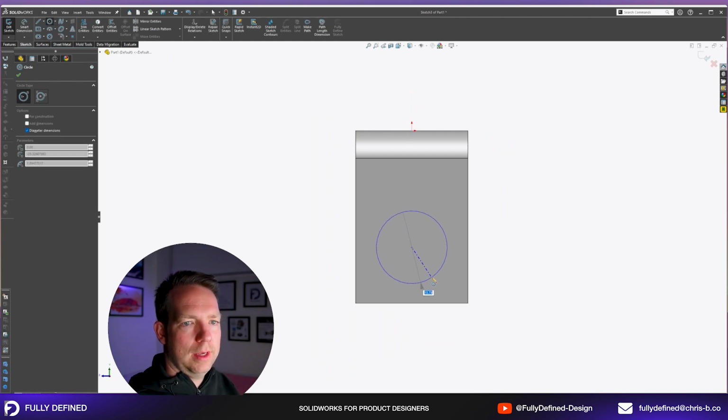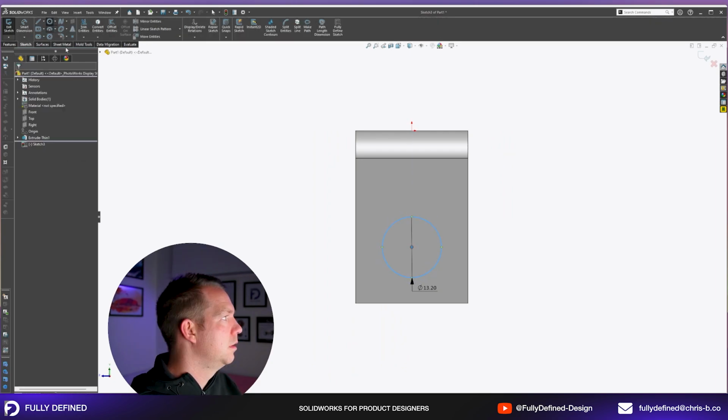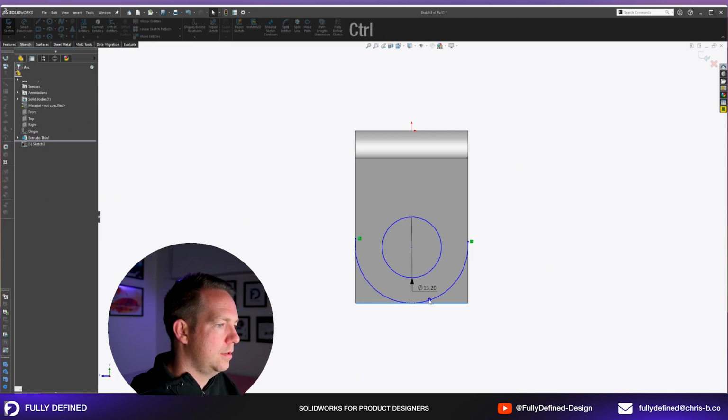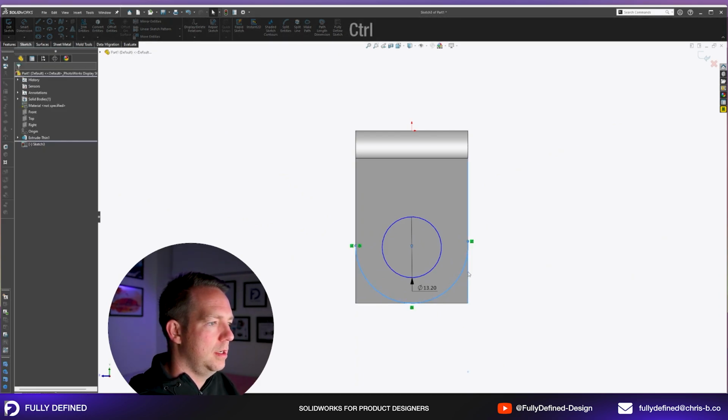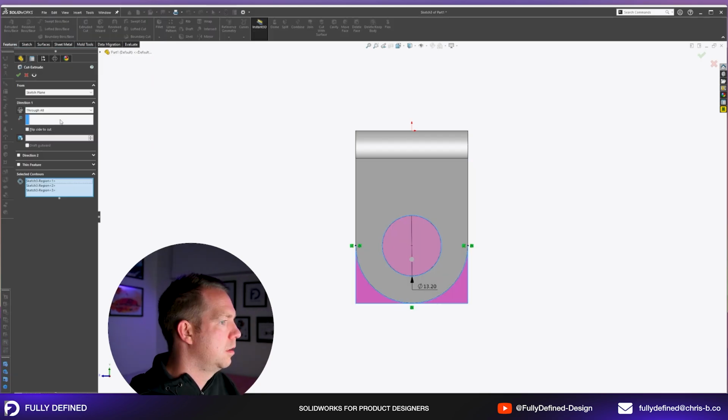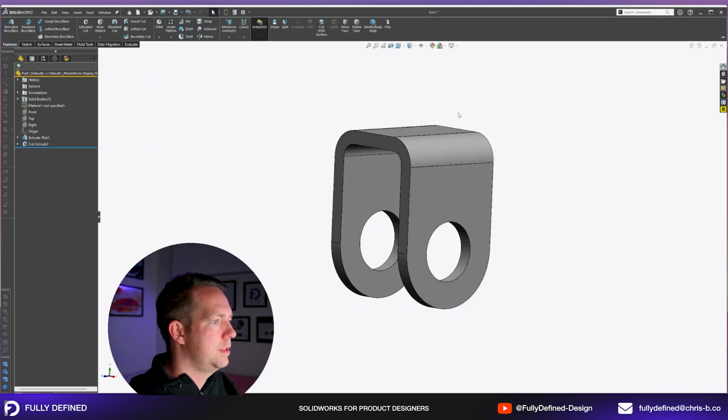And what do we have? Hole size here, 13.2 and then a 3.0 on the size. So at this stage, we're adding all the same references and dimensions that we've done in the originals. Okay, through all, that one's done.